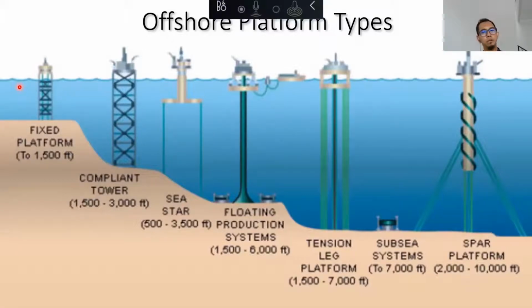So another rig comes, they bring all the service companies on board, and then they go to each of these platforms, depending on which operation they're going to perform. For example, a jackup will operate at a fixed platform. They will tow the jackup here, connect to the platform, set up the BOP, and then start drilling. But in deeper conditions, maybe with an anchored type, it's rare; semi-subs don't have any platform.